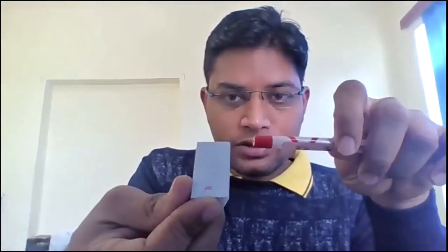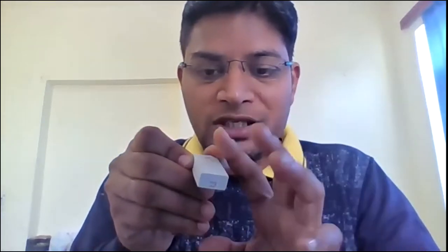Fine. Now, another is the shaft. Okay, this is the shaft, and if we mount the single point cutting tool like this, then either I should mount in this direction and move like that. Please focus here, either I can move in this direction, or if I'm mounting in this direction, then I can move like this. So either this side or this side, any one of these I have to consider.